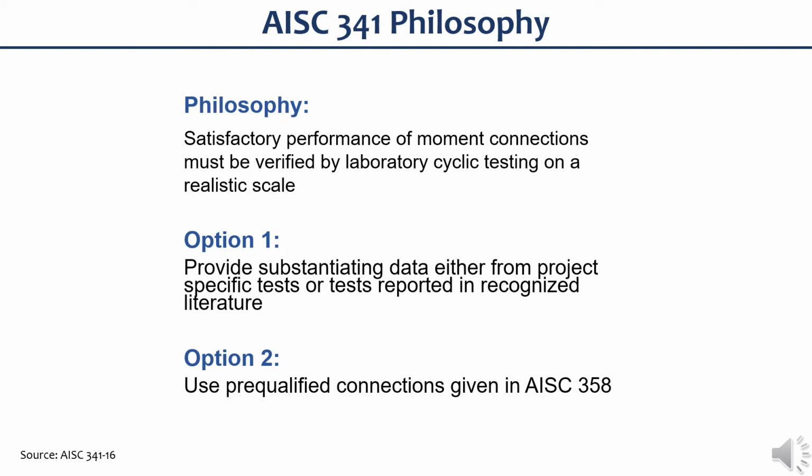Now, AISC 341 gives two options. The first option, the SER or the EOR, shall provide substantiating data either from project-specific tests or tests reported in recognized literature. Now, since performing such tests is expensive and time-consuming, a second option is provided to use the pre-qualified connections that is given in AISC 358.